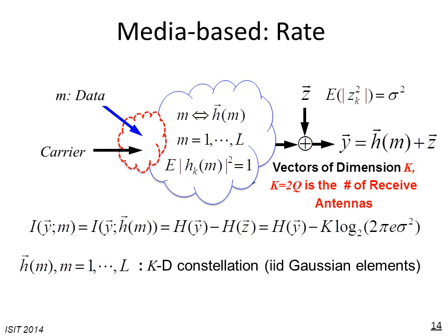And as you see, the expected value of the norm of that vector is 1, corresponding to the normalization of the fading. The channel is additive Gaussian noise, so I have the vector Z as the noise added. If my constellation has K receive antennas, this vector Z will have 2K IID Gaussian components with variance sigma square.